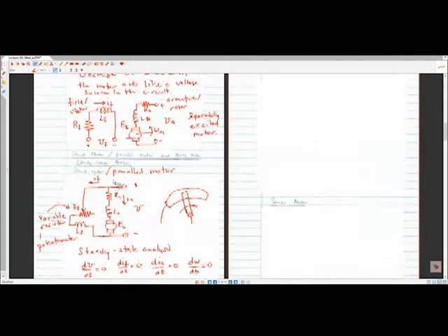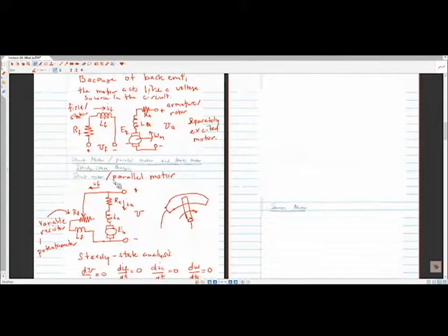Okay, so if we look at this from a circuit analysis, we have the current running through the armature. So we want to express IA. We almost consider that this inductor doesn't exist. The current can be given by the current going through this RA resistor. So that would be V minus EB over RA equals IA. We're using Ohm's law for that element of the circuit.